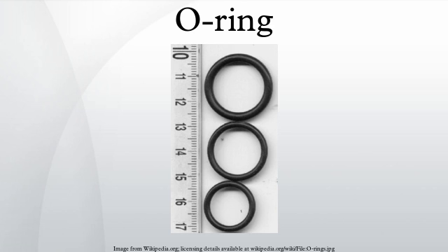At the low end, nearly all engineering materials become rigid and fail to seal. At the high end, the materials often burn or decompose. Chemical attack can degrade the material, start brittle cracks or cause it to swell. For example, NBR seals can crack when exposed to ozone gas at very low concentrations, unless protected.